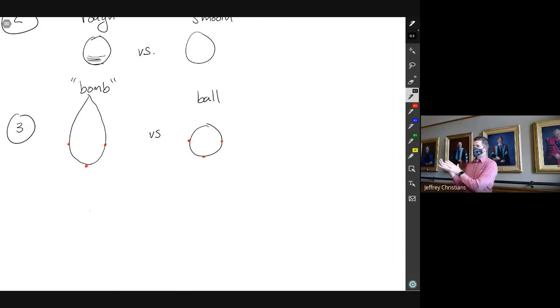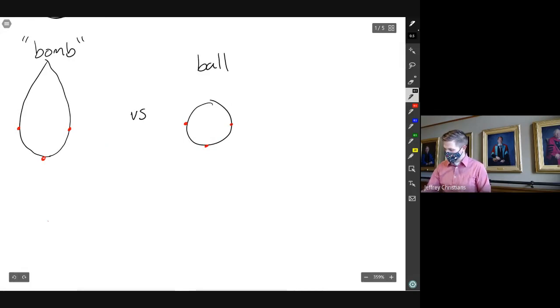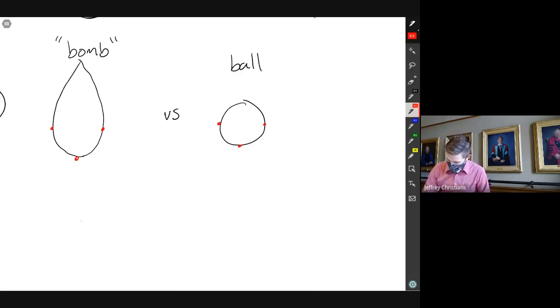If we think about what's happening in the context of the video that we watched before, where we looked at pressure and flow and looked at what happens to fluid boundary layers, maybe we can start to think a little bit better about this. So we have high pressure at the front end because the fluid's going to come in and crash into that front end and slow down. And as velocity goes down, pressure goes up.